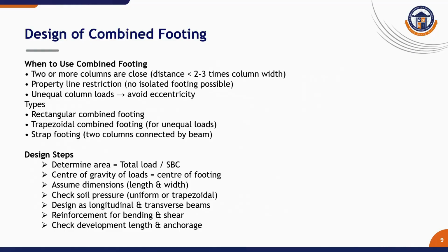Types of RC walls are plain concrete wall, which has no reinforcement, reinforced concrete wall with vertical and horizontal bars, and shear wall, which will be thick for lateral load resistance. Load on RC wall has to be axial load, either self weight plus superimposed, lateral wind or earthquake load.